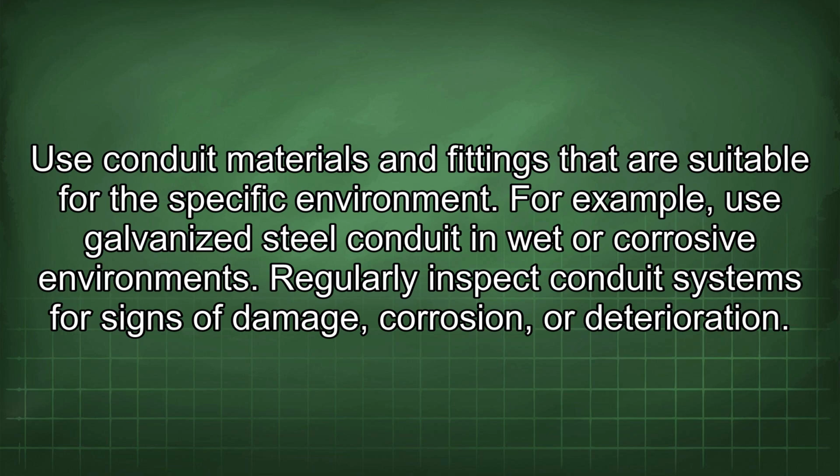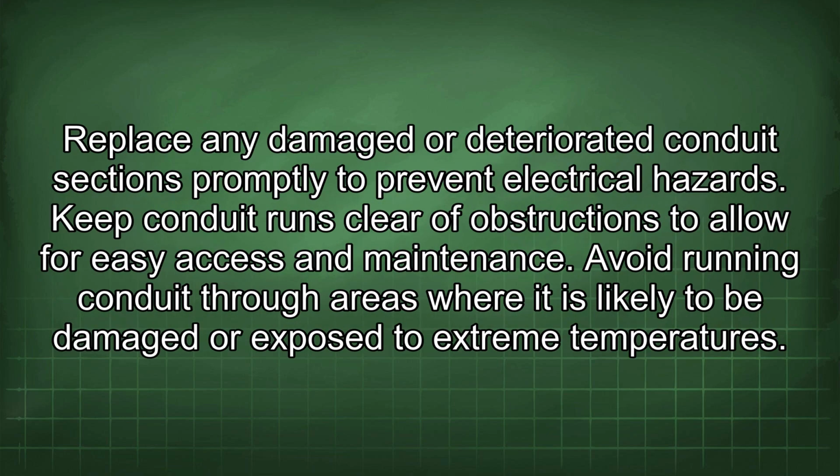Regularly inspect conduit systems for signs of damage, corrosion, or deterioration. Replace any damaged or deteriorated conduit sections promptly to prevent electrical hazards. Keep conduit runs clear of obstructions to allow for easy access and maintenance. Avoid running conduit through areas where it is likely to be damaged or exposed to extreme temperatures.